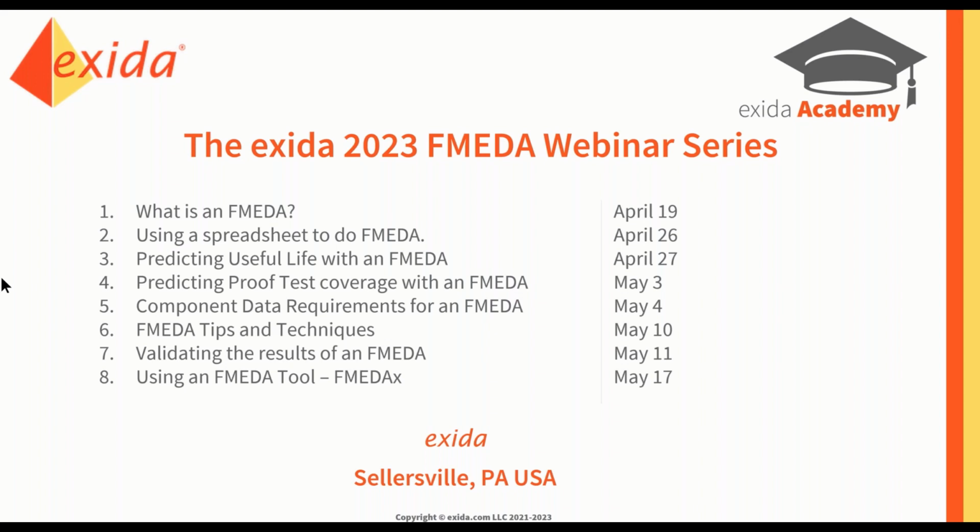And during that time, if your end of useful life will occur before the next shutdown, replace it right then and there, because you don't want to run past the end of useful life because your failure rate goes up and you're not getting the protection levels and the SIL levels you want.